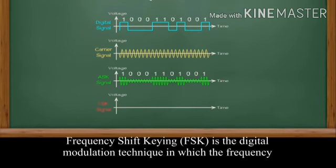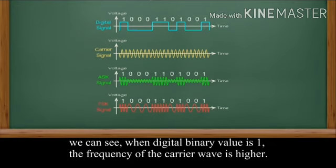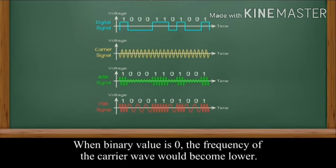Frequency shift keying is the digital modulation technique in which the frequency of the carrier wave changes with the digital signals. We can see when digital binary value is 1, the frequency of a carrier wave is higher. When binary value is 0, the frequency of a carrier wave would become lower.